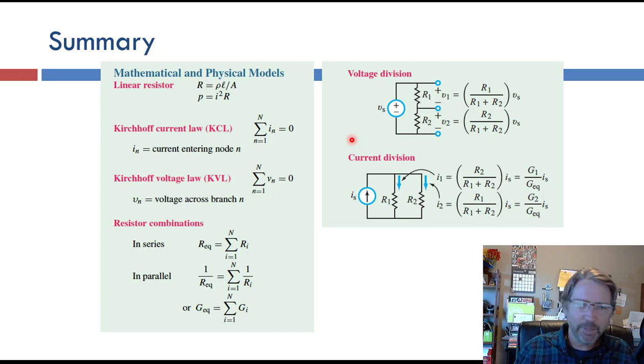All right, so as a summary, today we have looked at resistors. This is all of chapter 2 so far. V equals IR. Kirchhoff's current law, that's key. Use that one a lot. Current in equals current out. Kirchhoff's voltage law: as we go around any loop, any closed path, the sum of the voltages has to sum to 0.